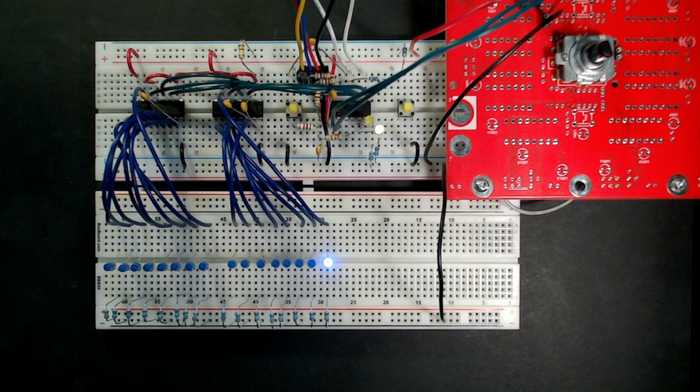This works perfectly. Alright, so we've leveraged the SPI mode of the serial port peripheral on the PIC microcontroller to control an arbitrary number of shift registers to display an arbitrary number of LEDs to indicate any level of intensity for our illumination system. Wow, and we did that using only 3 pins on our microcontroller. Incredible. Now let's see if we can do the same thing on the input side.